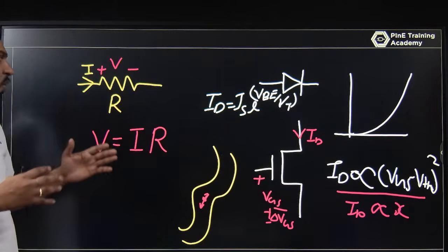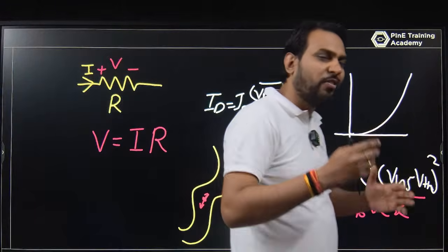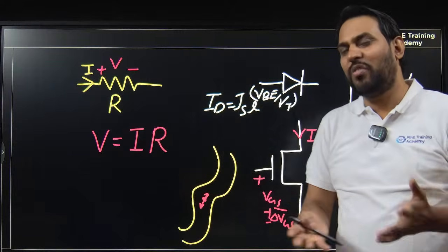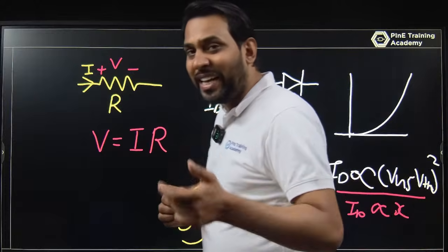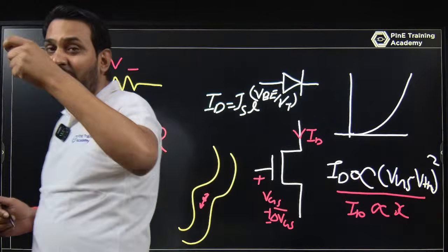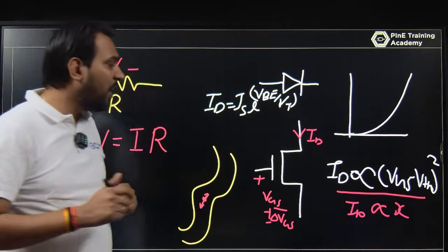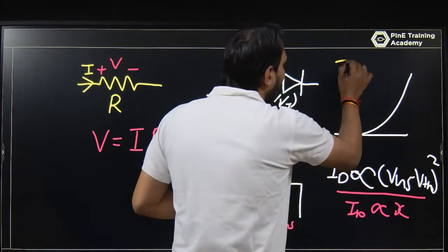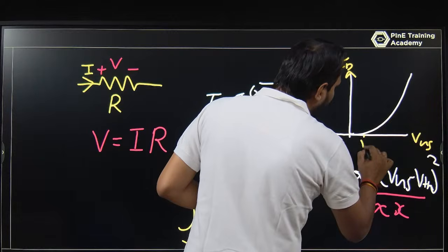Anyone can ask: you are saying that Ohm's law is valid for a linear circuit, so how can you use it in an IC? Because in an IC you have billions of transistors and the transistor is non-linear. We can think in this way: the MOSFET is non-linear. Let this be the graph of ID versus VGS of the MOSFET, and this is the threshold voltage.